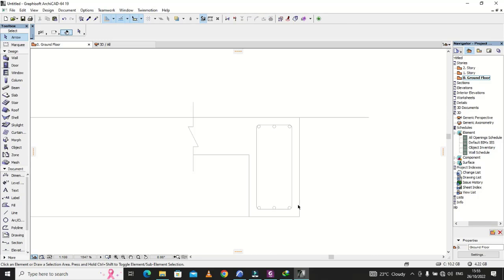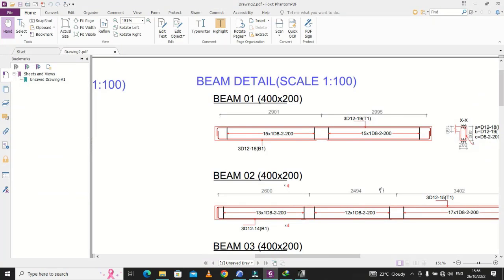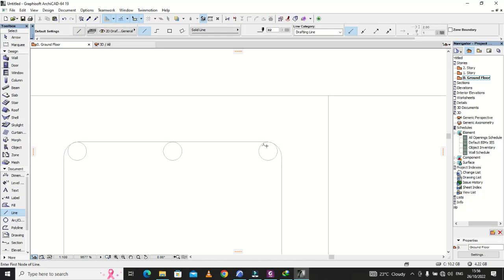So we already now have the reinforcement bars. So the next thing we shall do is to label the reinforcement bars like they have already labeled here. So you come here, so you forgot to put the hooks. So I shall just choose an arbitrary distance for the hooks.